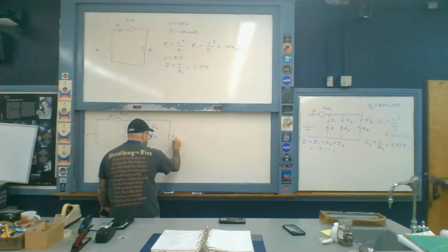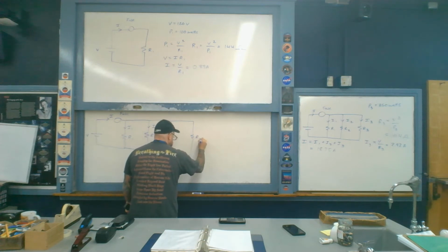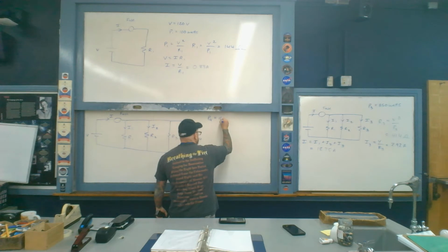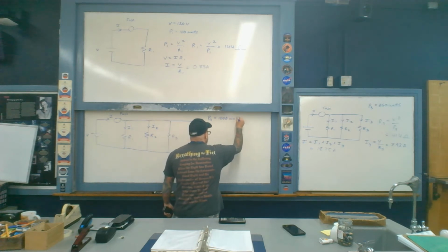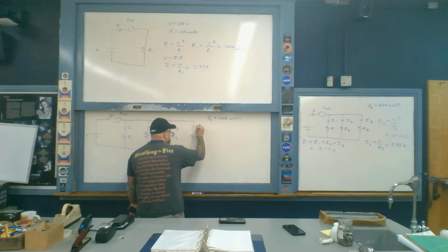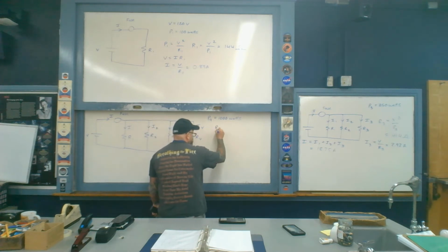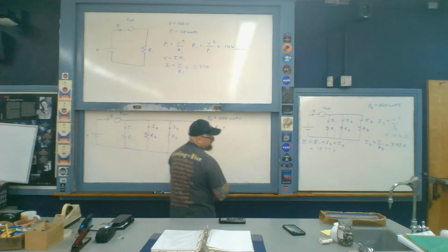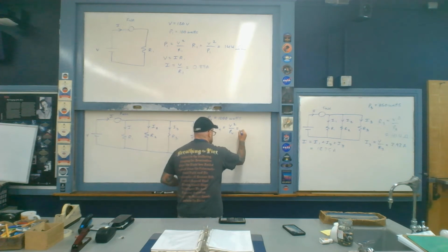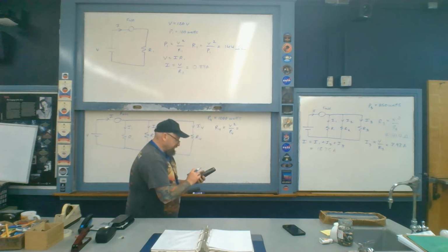So here's the R3 from before. And then right here is the R4. The power associated with that device is 1,000 watts. So we're going to have here once again I3 from earlier, and then I4. Now let's first of all figure out the resistance R4. We'll do so by once again using the same expression, V squared divided by P4 in this case. So that works out to be 120 squared over 1,000.